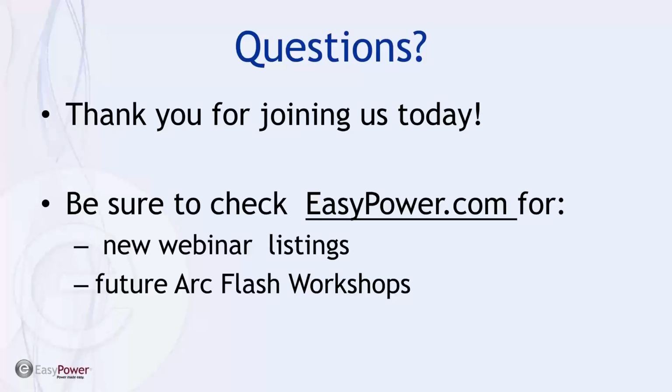The point that struck me, and Diana, her question doesn't emphasize it, is that when you change the settings in the base case, it doesn't override the scenario. Correct. Like I was saying, if I change the instantaneous setting or really anything, breaker settings or analysis options, all those things, that's not overriding anything in the base case. Any of those changes are being made in a scenario, recorded, played back and put on top of the base case. So there's no worry about overriding things in scenarios that you've made changes to.